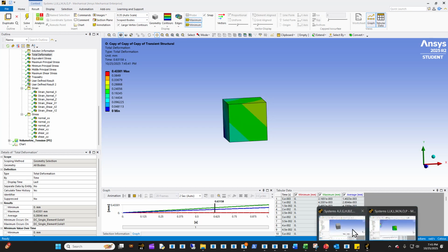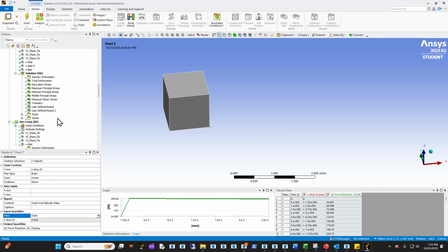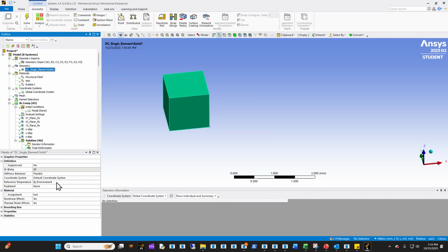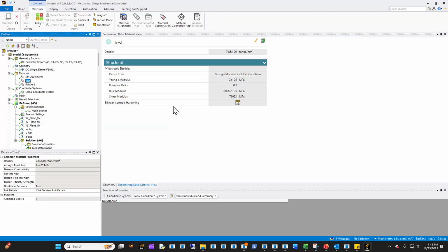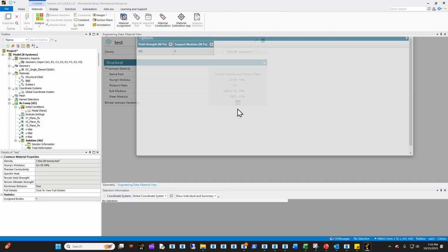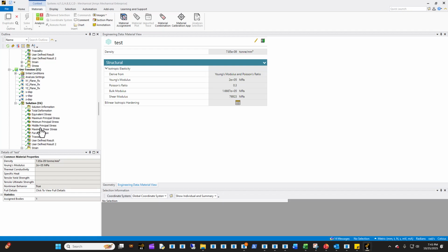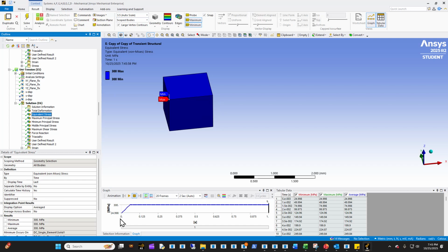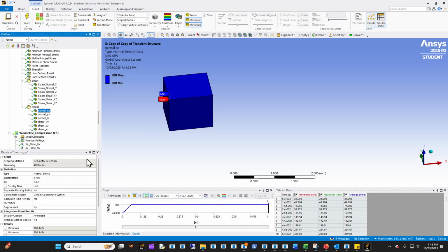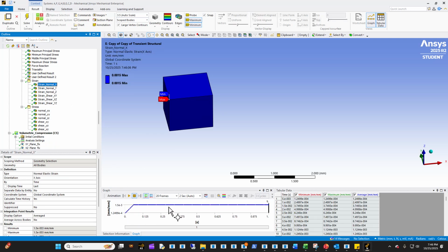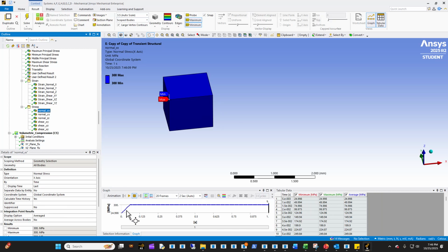One thing that you can test, right? In this case, what I have is a simple steel material. This is a test material, which is basically just a steel material with a yield strength of around 300. So what you do here, if you look at, for example, uniaxial tension, you have a linear ramping load until it reaches 300 stress, and then it just flattens out. And if I look at my normal stress, it's the same thing. Normal stress, shear strain, normal strain, right? So this is my normal stress because all I'm applying is a normal stress in this case, right?